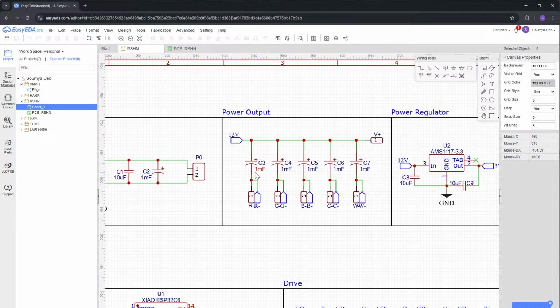I was planning to drive it at a pretty slow speed, roughly in the 1 kilohertz range. At 1 kilohertz, I would suggest against doing that. Do not drive LEDs at 1 kilohertz. That's also another thing, but that is very easily solved in software. I don't have to worry about it. I can easily change it to something above 20 kilohertz, and that will be fine.